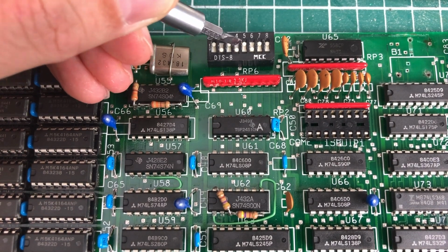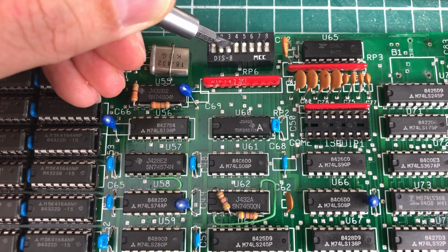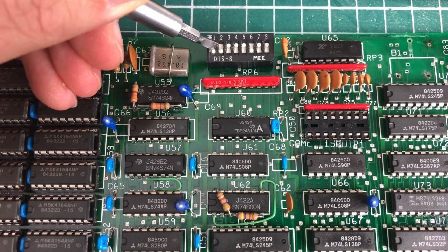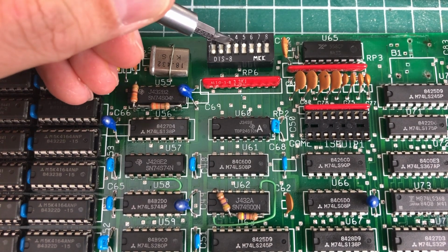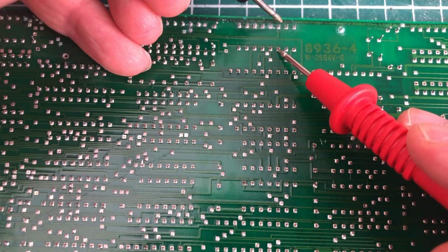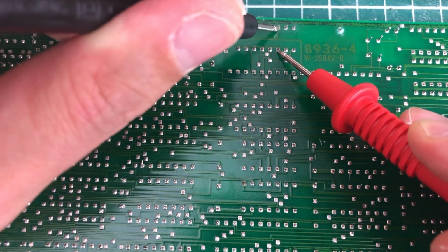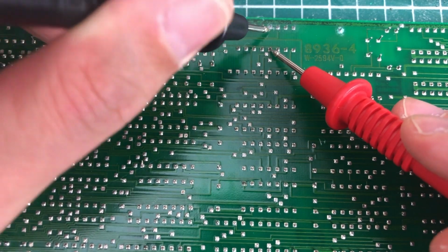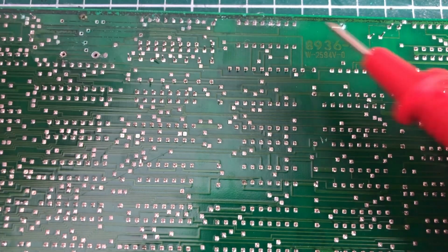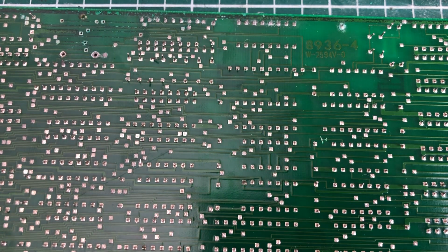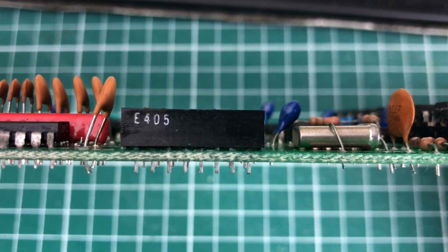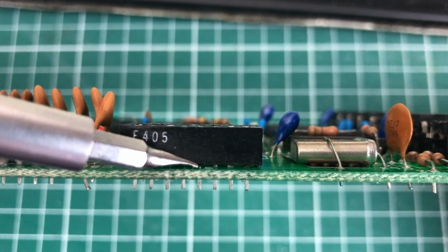Now, sometimes these switches can get stuck, or there can be some corrosion inside or beneath the switch block. So I'm just going to try switching them on and off again using this screwdriver here, just to make sure that they make a firm contact, and checking the continuity afterwards. But there was still no continuity, so the particular switch that enables the memory seems to be faulty. And if you look closely beneath the switch block, you do see some corrosion on these pins. So ideally we'll need to replace this switch block completely.